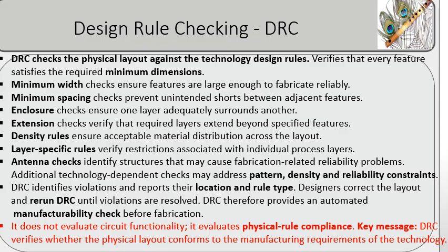Importantly, DRC is primarily a physical manufacturability check. It determines whether the layout follows the geometric and manufacturing constraints of the technology. Thus, DRC provides an essential verification step between layout creation and fabrication.